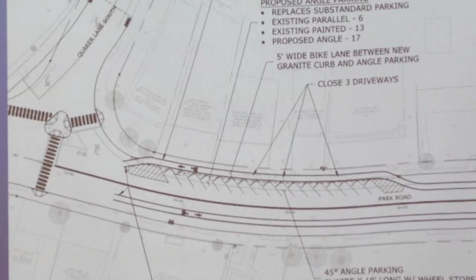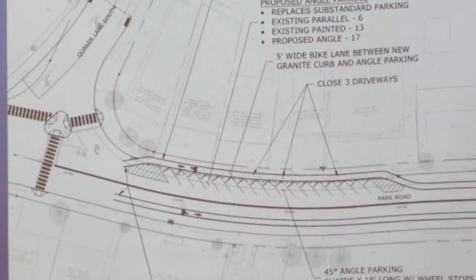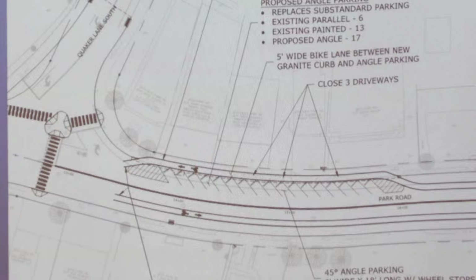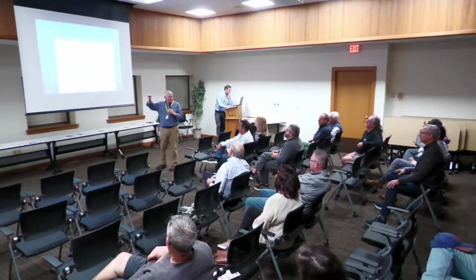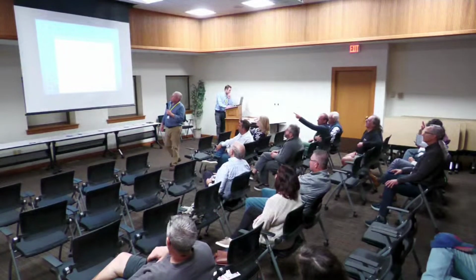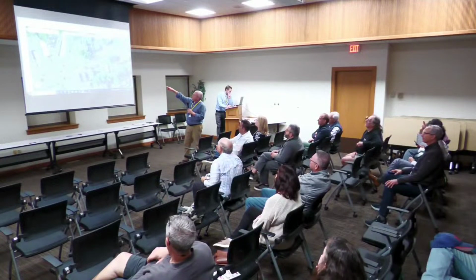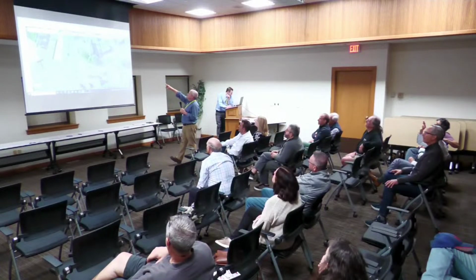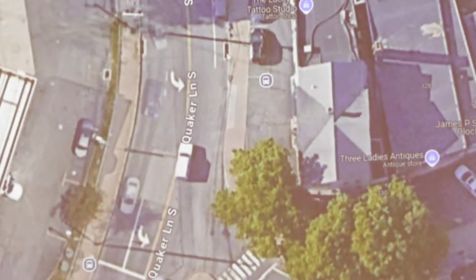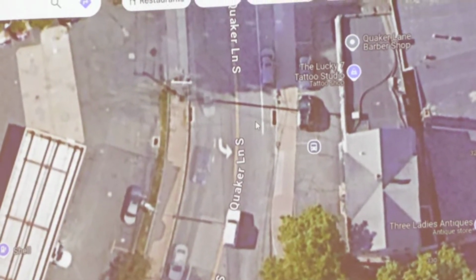My question is, how far up does the paving go? I understand it goes to that dotted line, I was just saying, where is the dotted line? Is it beyond that commercial strip? No, it's before the driveway into that commercial area that goes in behind the restaurants. You can see the depth of the building. So just before the gas station driveway and before the driveway to turn into where Sweet Tea is. There you go. Greg, the double catch basins are basically the limit. Just beyond those two catch basins is where the paving limit is, just before the driveway to the Shell.